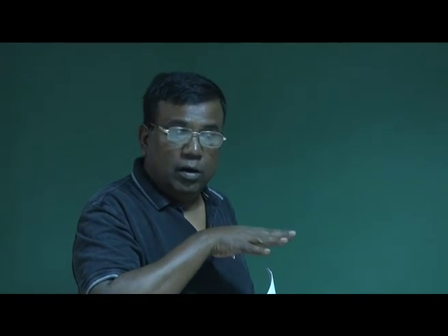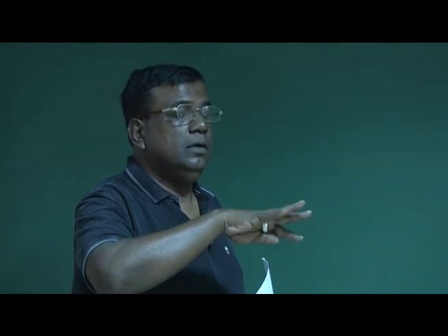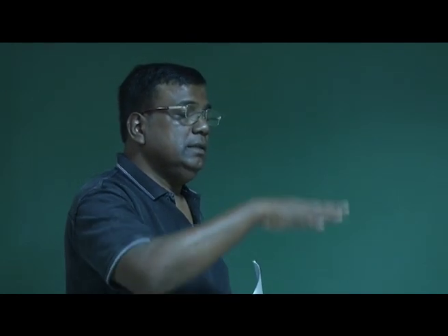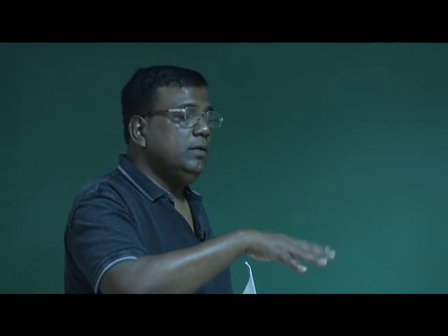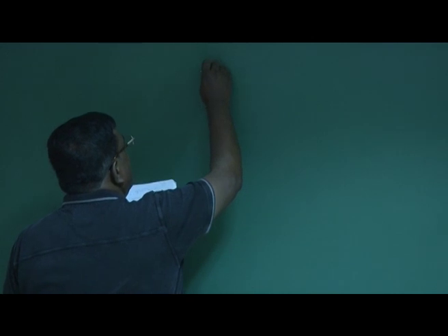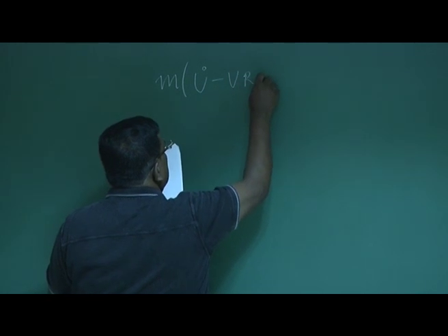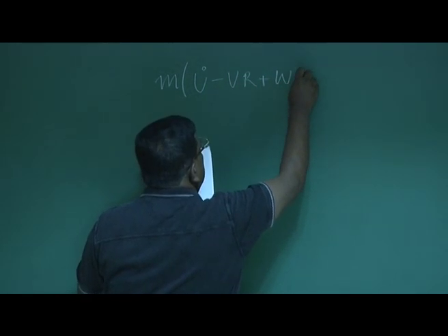Okay. Remember that we have u dot, v dot, w dot, p dot, q dot, r dot equations, but since I am talking about longitudinal case, that means I am talking about a motion in the vertical plane. So I will be bothered about u dot, not v dot. Okay. I will not be bothered about roll. I am talking about longitudinal. So it's u dot, then this is w dot, plunging, and also the pitching, right? So three equations we will take for consideration, and one is m